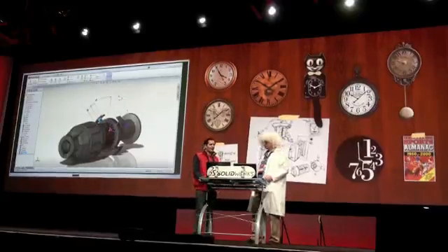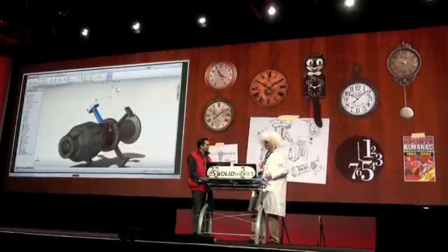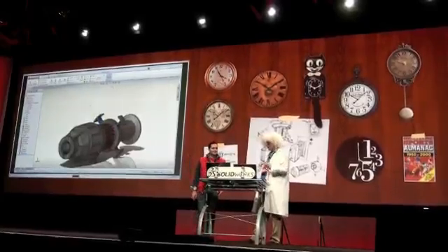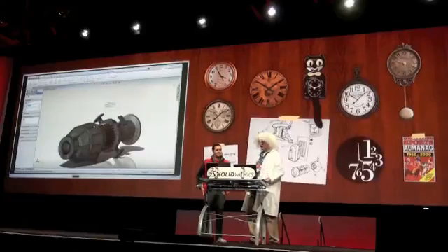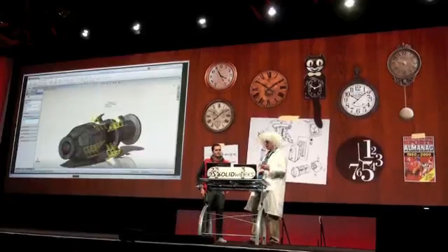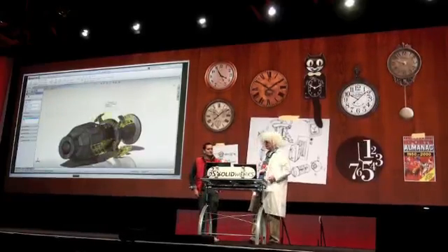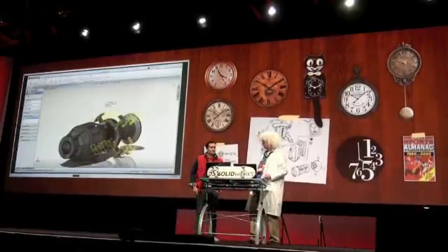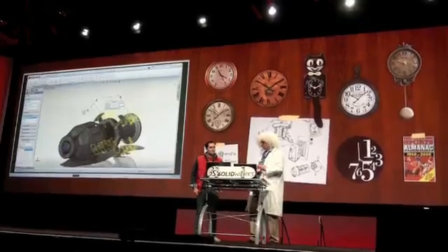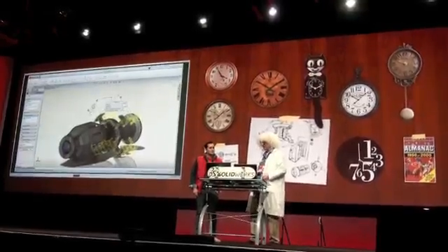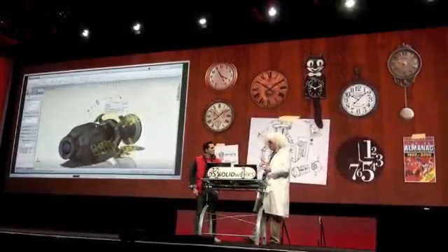That's great, Doc. I really like the look of this so far. Yep, but I know how you like fancy designs. So how about for some added flair, let's pattern these fins. Now it'd be pretty boring to use the same size, so in SolidWorks 2013 you can vary pattern instances just by selecting the dimensions you want to change. So we can add as many parameters as we want. Let's change the width of the vane, the angle, and how about the depth?